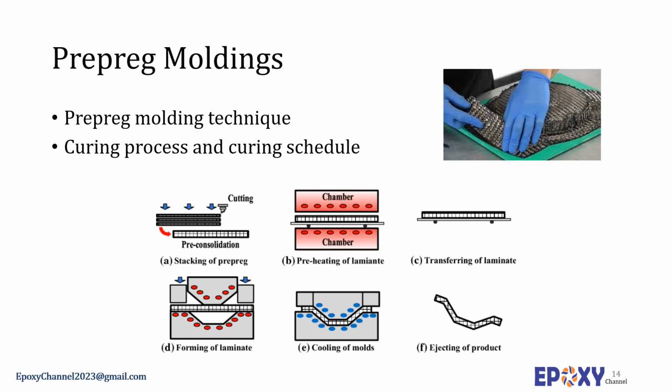High-performance carbon fiber and glass fiber laminates are fabricated by prepreg molding using autoclave or pressclave, a small autoclave with flat platen press techniques. A prepreg consists of fibers or woven cloths pre-impregnated with the epoxy resins modified with a thermoplastic or elastomeric toughening agent and containing a latent hardener. The latent hardener, such as insoluble dicy, is micron size in the resin solution prior to wet impregnation of fibers. The curing can be adjusted by incorporation of a promoter or an accelerator.